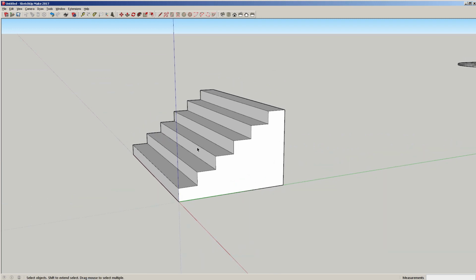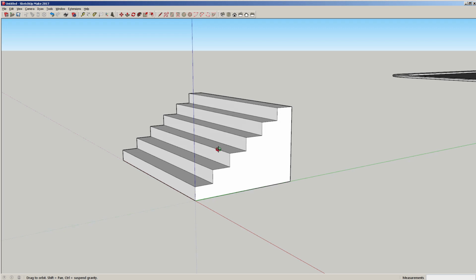Let's create our rail. Just like a couple lessons ago, we can draw a line literally from the first step to the last step. And this height will determine how high your ledge is, or sorry, your rail. We already know how high the ledge is, so I did 2. Sometimes you can snap by rolling your mouse over here, and sometimes it'll find the angle that you want. Not always, so that's fine.